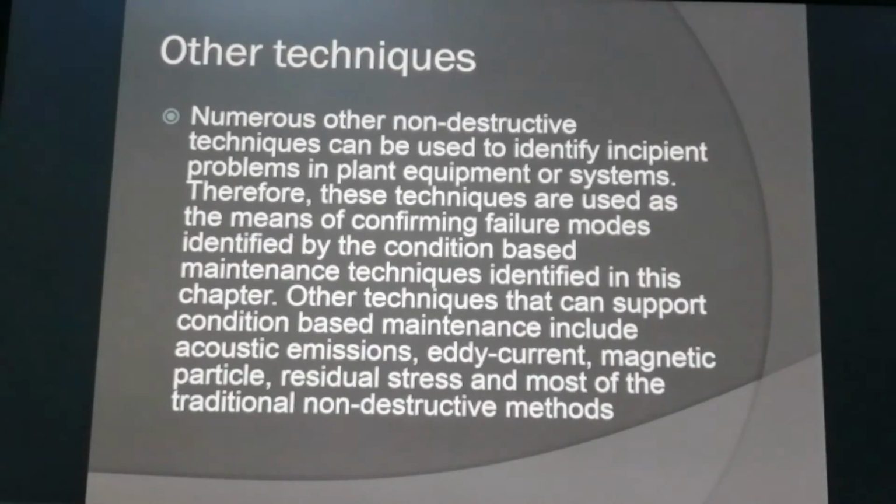Other techniques. Numerous other non-destructive techniques can be used to identify incipient problems in plant equipment or systems. These techniques are used as the means of confirming failure modes identified by the condition-based maintenance techniques identified in this chapter. Other techniques that can support condition-based maintenance include acoustic emission, eddy current, magnetic particle, residual stress, and most of the traditional non-destructive methods.